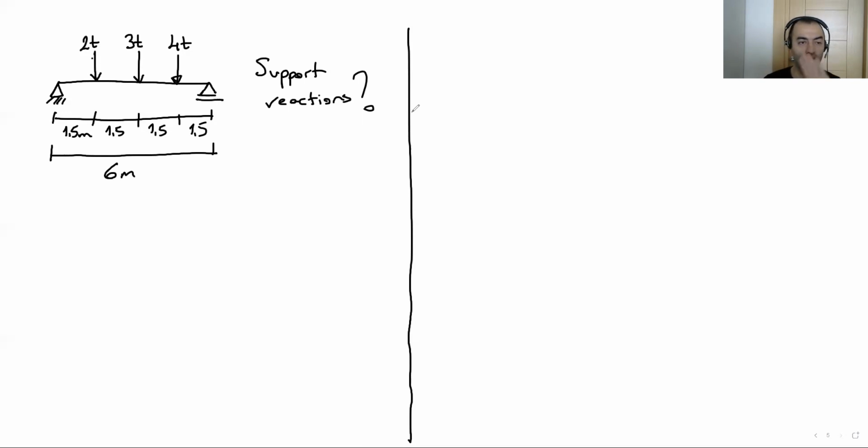When we get a structural system, firstly, we are going to put the unknown support reactions on the sketch. After that, if we have any distributed load, we are going to convert it to a point load. This is a kind of preparation for the calculations. Firstly, we do all this and then start the calculation, right?